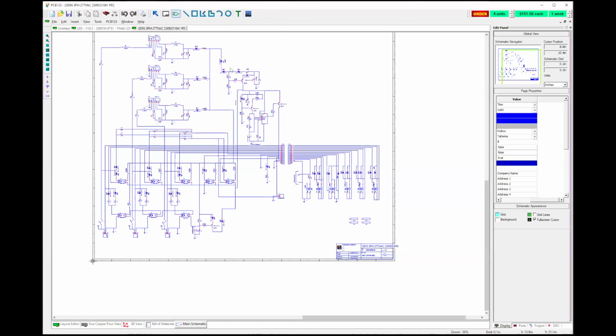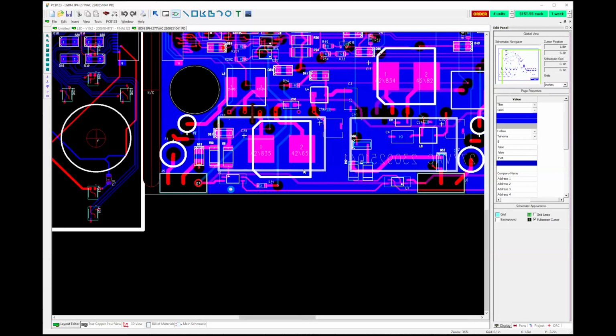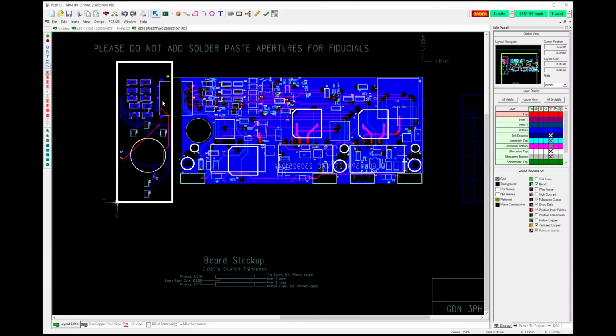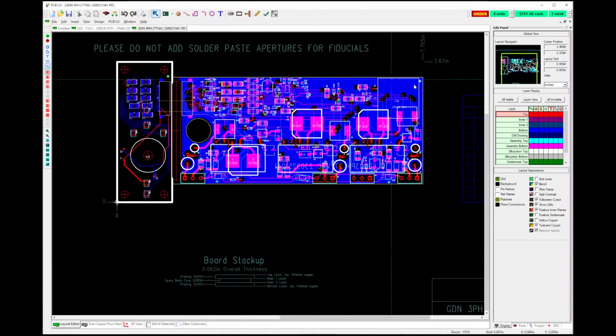And I try and do my schematics sort of along the lines of how the circuit board's going to be laid out, so I can have some correlation to that. You can't do it exactly, but it makes a lot more sense that way. And then again, you can modify your board to fit the necessary physical parameters. This is 2 circuit boards that plug together with a ribbon cable. So I put a slot here so I can just clip the 2 boards apart and off we go. And this area features a slot. This is a cutout. It fits over a boss on a part.